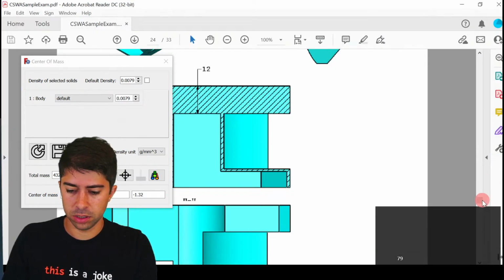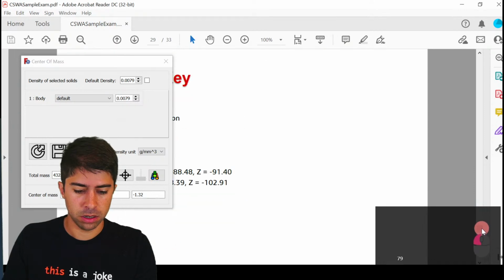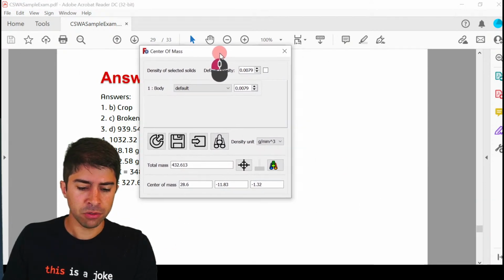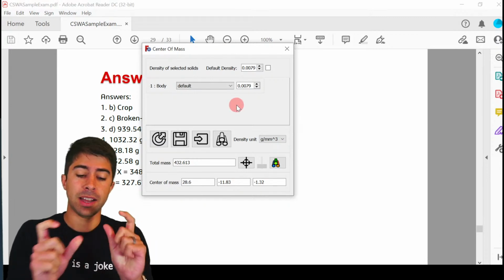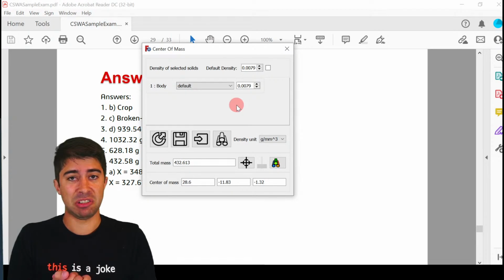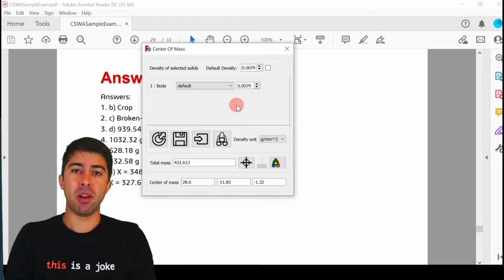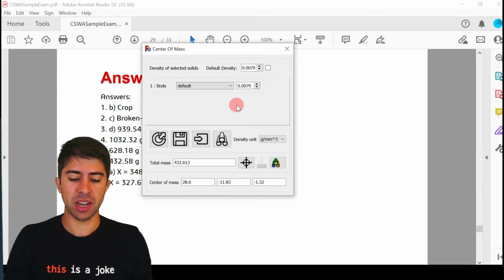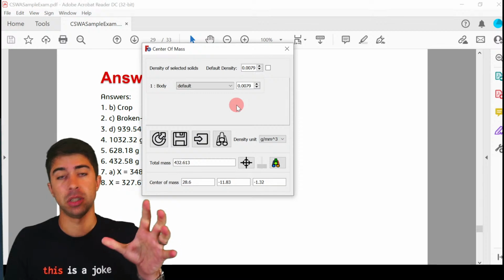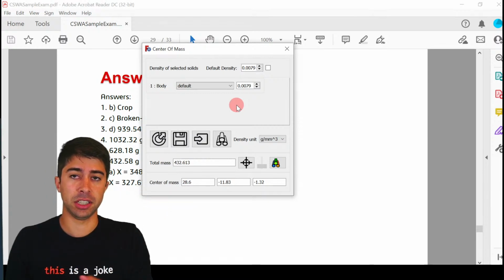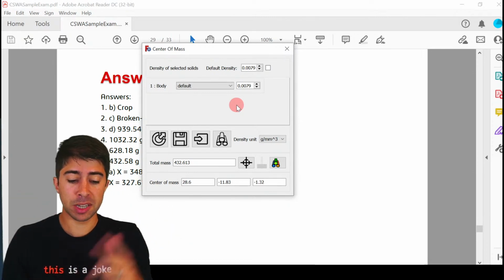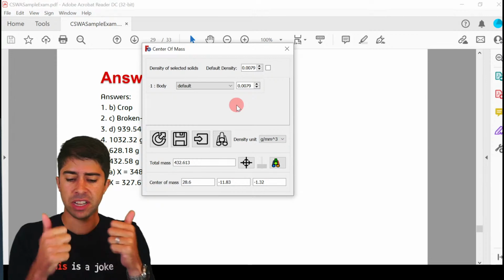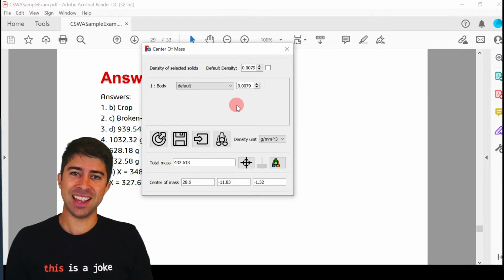Let's go have a look and see if that is in fact our value. 432.58. This one is 430.61. Now that discrepancy is as a result of my very rough offset entities for that wall thickness. So I guess that difference came as a result of that. Obviously, if it was in SolidWorks, you just have that very nice convert entities or offset entities, and you specify 1 millimeter, and it would have done that. But this is within 1% error, so that still goes. So yeah, I'm happy with that.